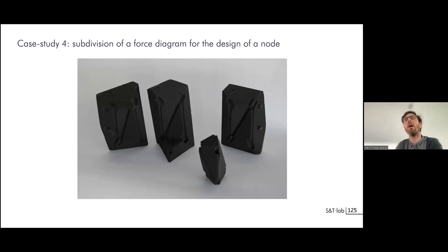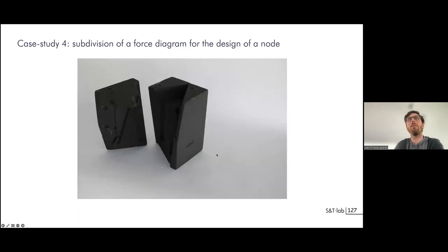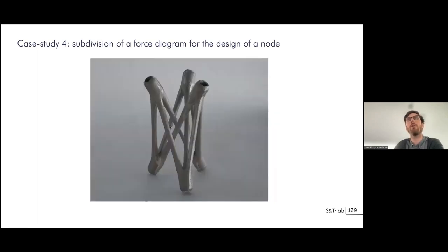So it's a 3D print of sand printing. In 3D, you have the different pieces of the mold. So you can assemble them together. This one goes in the center, and this one, and this one. And from there on top, we cast the aluminum. And so the result was this node. And so I will use this last example to conclude my talk of today.